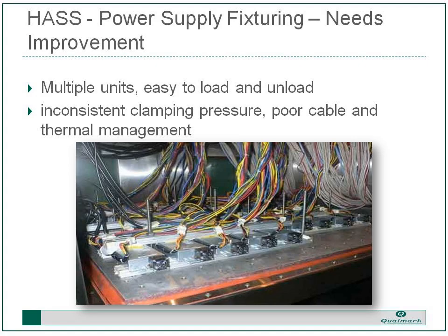And just to give you an idea of some steps that had been gone through by a customer, here is fixturing for HASS. Power supply fixturing, it's okay, but it's not great. It is easy to load and unload, but we have inconsistent clamping pressures across here. If you look here, we have a clamp on this end and a clamp on this end of this bar, and that bar goes all the way across the products to clamp down.